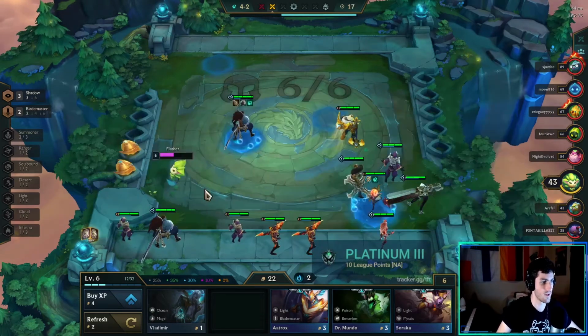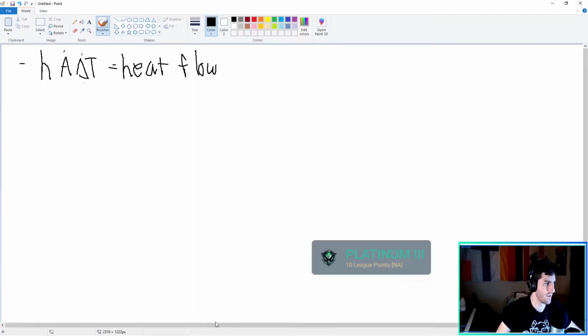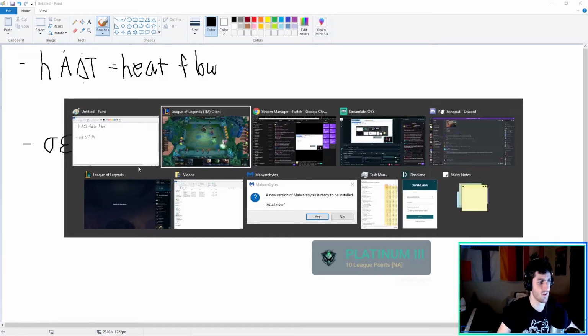Okay. The similar term for radiation is here, and so it says that the radiation heat flow is equal to this times negative, is it? Delta T to the fourth. So this means you fourth power your T's. So instead of T atmosphere minus T surface, it would be T atmosphere to the fourth minus T surface to the fourth, times area. So that's the radiation term.